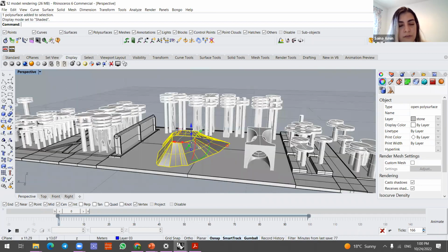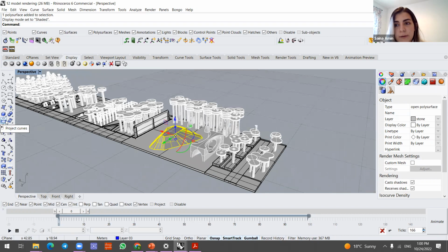And after that, for example, when we finish the modeling, you can create your geometry directly from this tab. For example, go for some intersections or whatever with solid. It's another way that you can make sure that your mesh is closed and you have the solid one. Or you can start modeling, for example, with the cube or rectangular one, and after that, project your curve on that, and do the whole process from the reverse side. There is no difference, or for example, you can even do it with a pyramid, and that would be good. And whenever you have no lone edges, it's good.